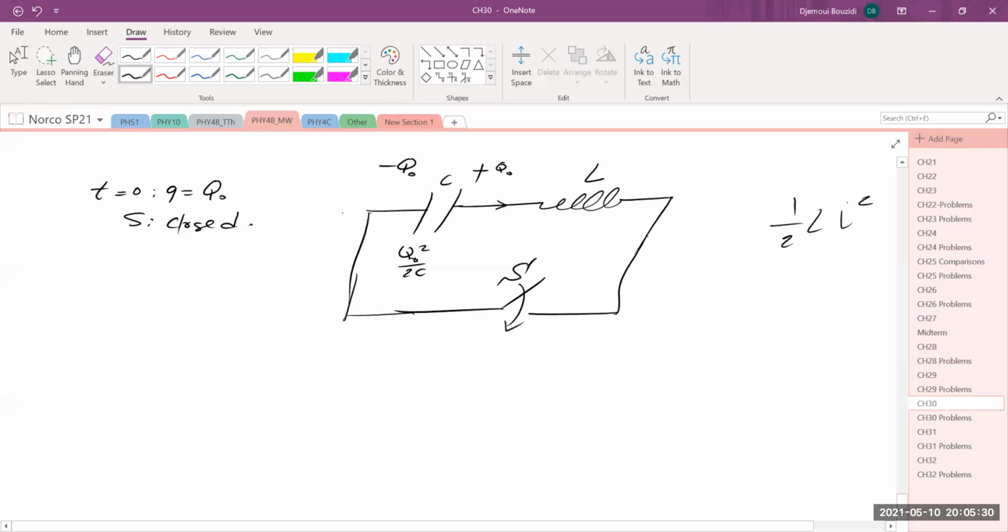So now the capacitor will push current in the opposite direction, but the inductor will oppose it still and build up energy in the process. And the capacitor will lose energy in the process, and at some point they will run out of all of these Q charges in the opposite direction, and there will be a current now going through the inductor. At that point, the inductor will step in to continue pushing the current, because it doesn't like the current to change at all. The fact that the capacitor runs out of energy will mean that the inductor has to push the current until it runs out of its energy, and so on and so forth.